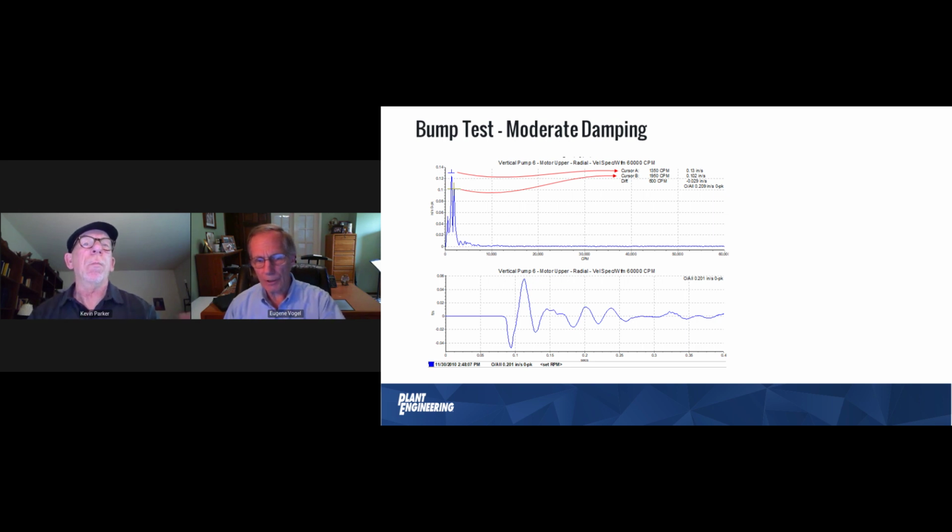Can you see a particular frequency through there? How much is there at that particular frequency? Well, what if I checked at a different frequency? It looks at all the different frequencies that might be present and plots them out. That's the plot on the top, and it's called a spectrum. Some people call it an FFT, a fast Fourier transformation.